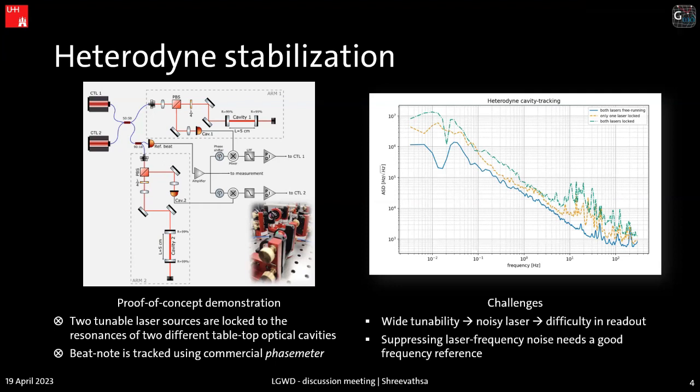I had a small query. These phase meter and the distance measurement and displacement measurements using interferometry are fantastic if your distances are very large. And I believe the intention here is to measure the small gap change between the proof mass and a frame in the case of the seismometer, right? So how does it compare with techniques like capacitance sensing or evanescent sensing in terms of residual noise? Can you throw some light on how it compares?